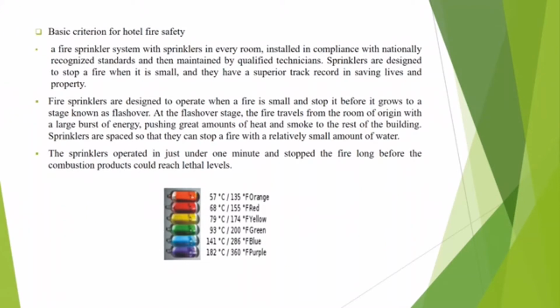How does the fire sprinkler work? Each closed-head sprinkler is held closed by either a heat-sensitive glass bulb or a two-part metal link held together with fusible alloy. The glass bulb applies pressure to a pipe cap which acts as a plug that prevents water from flowing until the ambient temperature around the sprinkler reaches the design activation temperature of the individual sprinkler head.